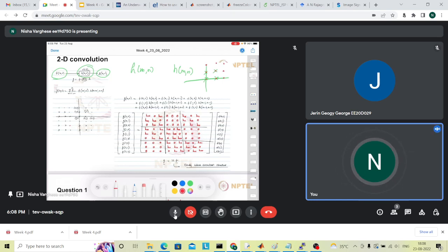So sir explained how to get circular convolution, and how to get the linear convolution answer by using circular convolution. He wrote the equations here, and at last a matrix is formed, an equation like G vector is equal to H times F vector. So it is derived, and H can be written as a doubly block circular matrix.